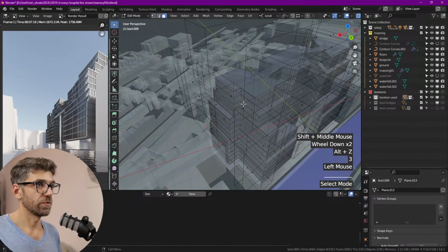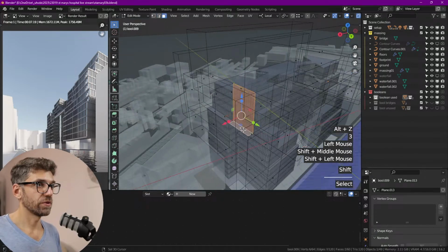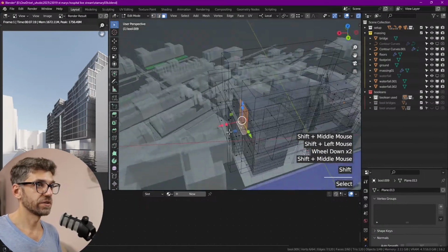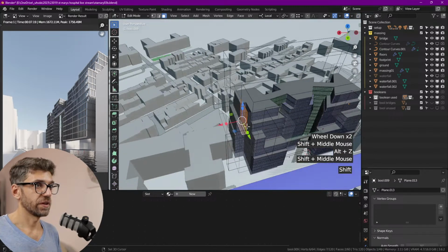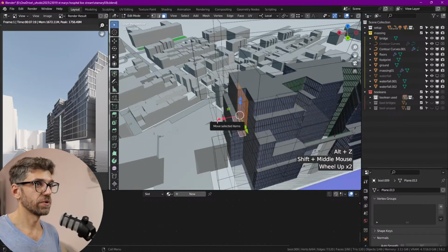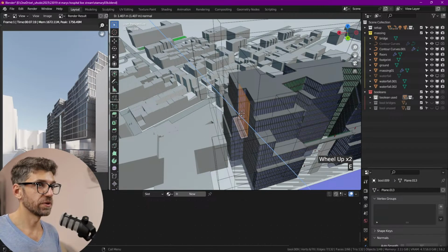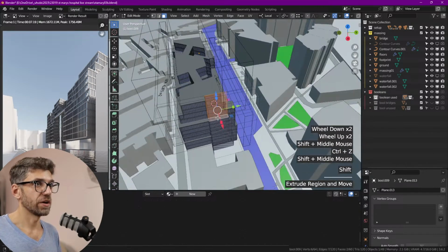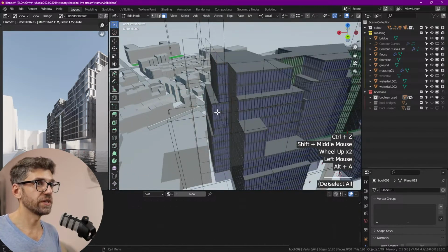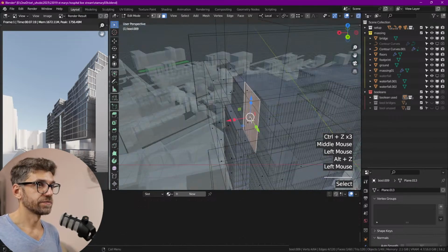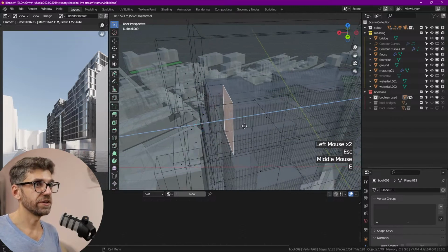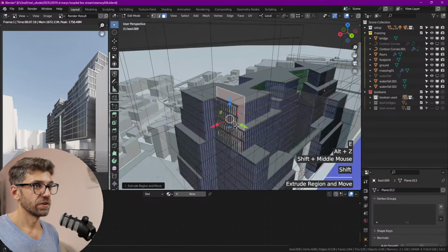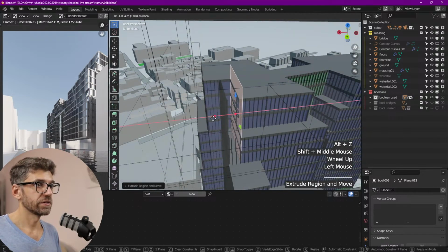And now we're going to grab these two faces. Yep. And let's push them. Well, first we want to extrude them. Now we're extruding in a very strange direction. It's because we have that bottom. We don't need that bottom, I suppose. Let's undo that because... Did we extrude? No, we didn't. Okay, so now extrude just this face. That's all we need to extrude. Okay. So that's getting there.